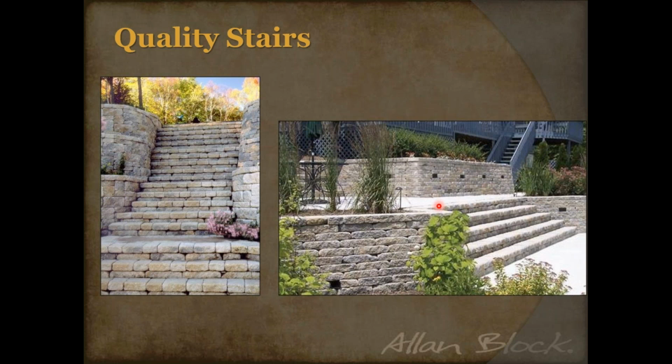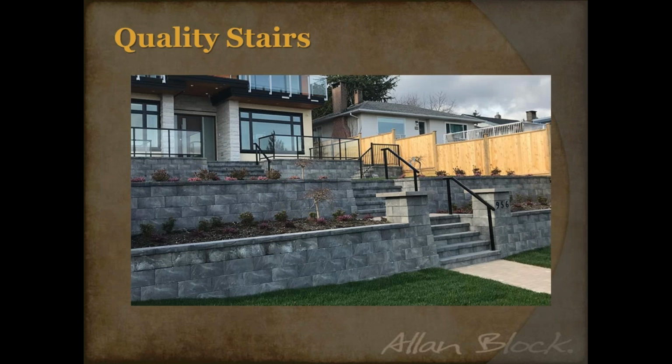And so keep that in mind. The blocks do have a setback. Like I said, for the classics, it's about 1.25 inches per foot. And once you know that, it makes it a lot easier for you to lay that out. Here's another example where they just kind of did a couple terraced walls to work through that and kind of blend that together.